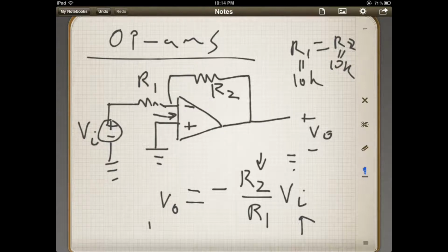So your V out would be -1 times your V in, right? So it basically will invert your output. And that's hence why they call it an inverting op-amp, okay? And then what's great is, depending on this resistor ratio right here, you can multiply it. You can actually add some gain to it, okay? So what it will do is make that negative number either bigger or smaller, depending on what values of R1 and R2. And it can be any combination you want.